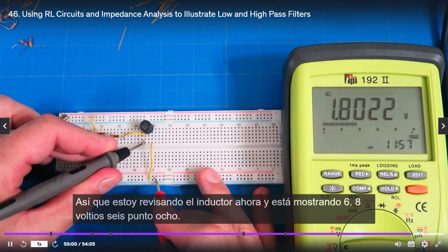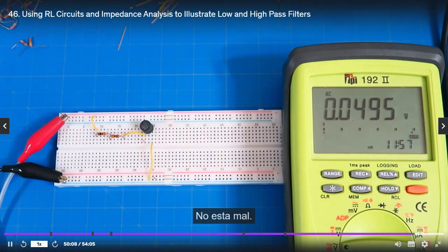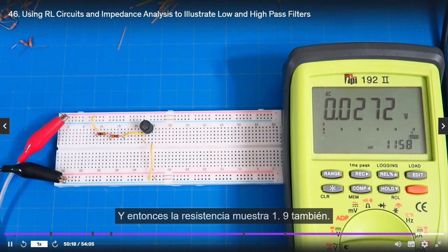So I'm going over the inductor now. And it's showing 6.8 volts, 6.8. All right, that's not bad. And then our simulation, if you go back here, so let's take a look at the simulation. So the simulation is showing 6.8 volts as well. And so over the resistor, it's showing 1.92.